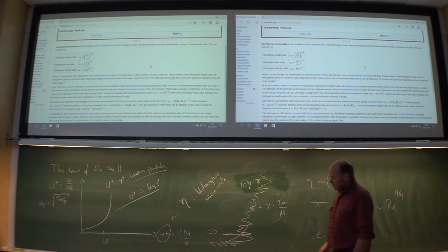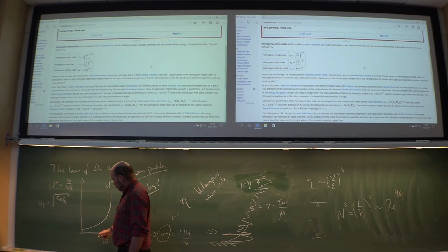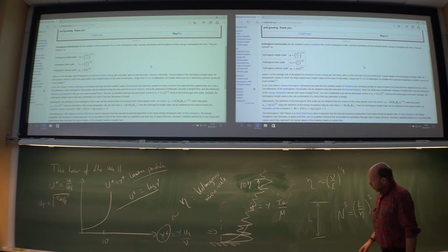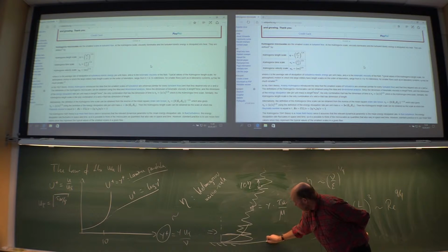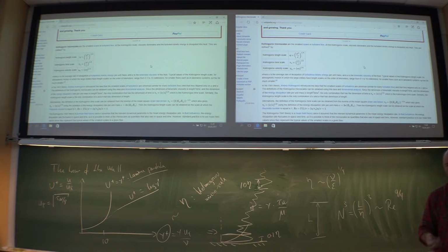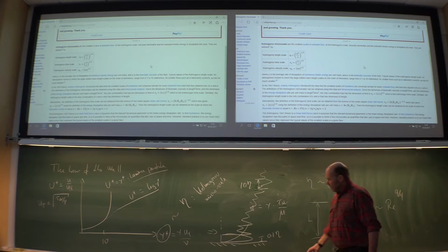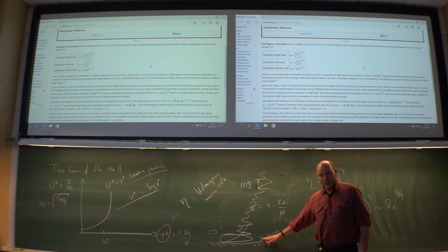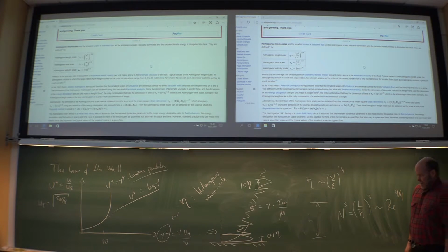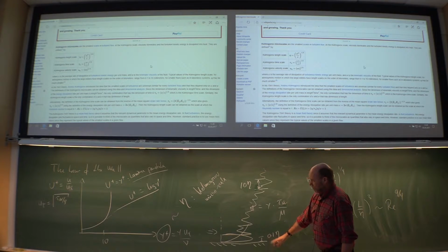On the other side, getting very, very close to the wall, your smallest cell should actually be 0.1 Kolmogorov, 1/10 of the Kolmogorov. You really have to resolve this layer very, very close to the walls. That's unavoidable. That's where all the action takes place. That's where the turbulence is born. Of course, you need control. So very, very small cells down here.